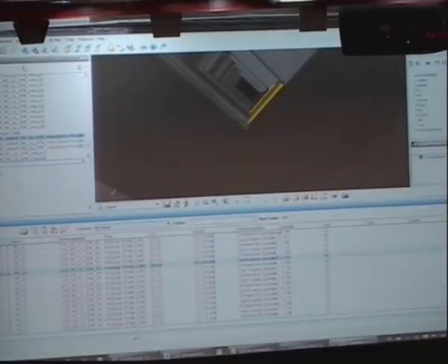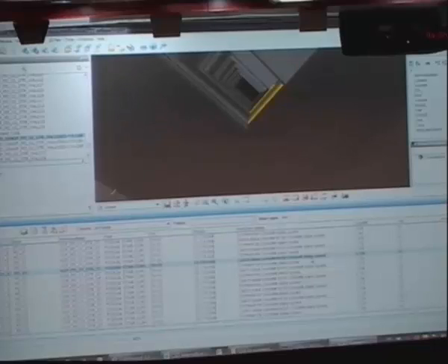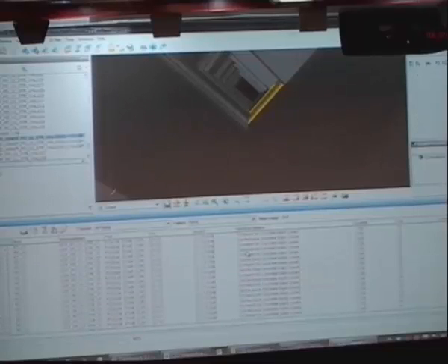By applying this filter, you can see that we actually have two results coming back to us. We have the formwork and we have the concrete. In my case, I want only the formwork. I can again do it two ways. I can go in and change the filter from inside, or I can just make my life easy and add a filter here in the quick search to include only the formwork.